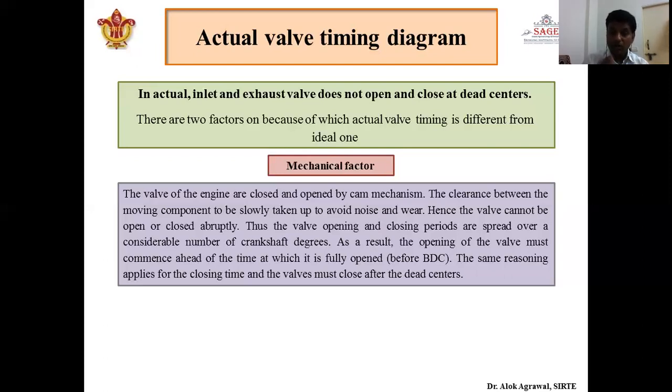Similarly, we cannot close the inlet valve at the bottom dead center because again it will take some time, and because of the inertia of the fluid we want the maximum amount of air and fuel to be inducted into the combustion chamber so that the maximum amount of power is produced. So we will close the inlet valve after BDC, to allow a large amount of fuel and air mixture to get inside.